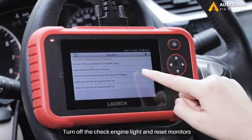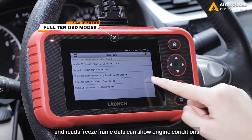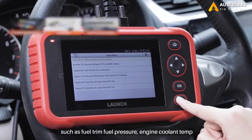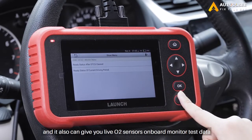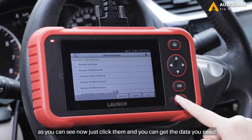Turn off the check engine light and reset monitors. By the way, this tool supports full OBD modes, and reading freeze frame data can show engine conditions such as fuel trim, fuel pressure, engine coolant temp at the time the malfunction indicator lamp was set. And it also can give you live O2 sensor onboard monitor test data. As you can see now, just click them and you can get the data you need.